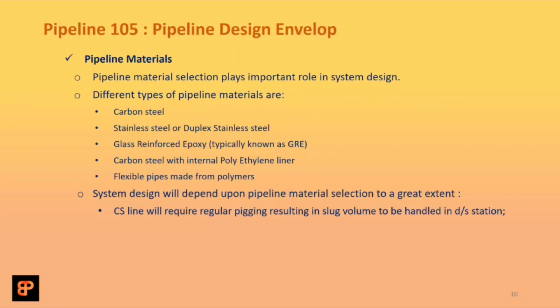At such low points, stagnant liquids will accumulate, and those will have a detrimental corrosion impact on the pipe. The corrosion normally starts at the 6 o'clock position in the pipe, and to avoid that from happening, we need to keep removing these liquids regularly from these low points.